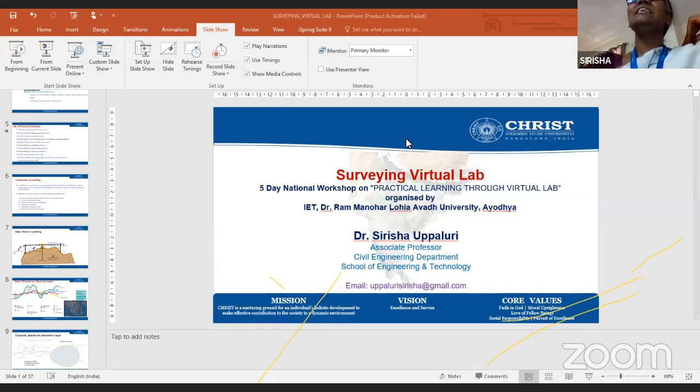Okay, this is not an easy task to perform like that. If you have GIS software or photogrammetric software, you can convert those ellipsoidal heights to MSL heights easily. But manually, it is a difficult task to convert the values from ellipsoidal heights to geoid MSL heights. It is difficult, but MSL heights to ellipsoidal heights you can convert because it is a scale change.